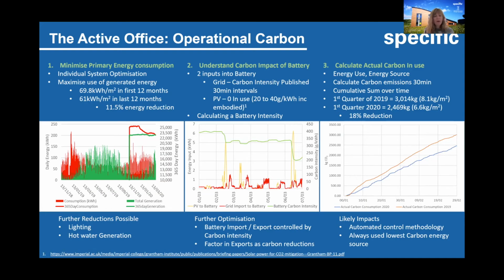So there are two primary challenges when tackling carbon intensity in use. The first is energy use reduction. Using the extensive data available, we were able to clearly identify systems for energy reduction. Sometimes this was based on better control, set points, timing, or setback temperatures. Other times this involved modifying the systems to enable lower temperature heating while maintaining the heating power.